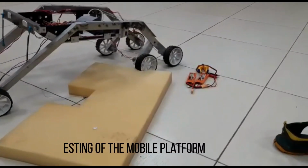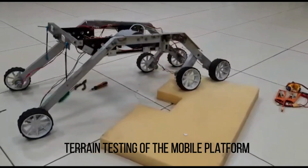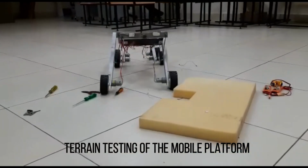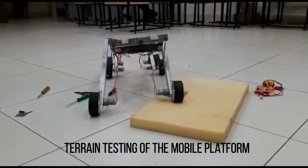The rocker bogey mechanism consists of no springs. Stub axles in each wheel allow the chassis to climb over obstacles such as rocks, ditches and sand. The chassis plays a vital role to maintain an average pitch angle of both rockers by allowing both rockers to move as per the situation.